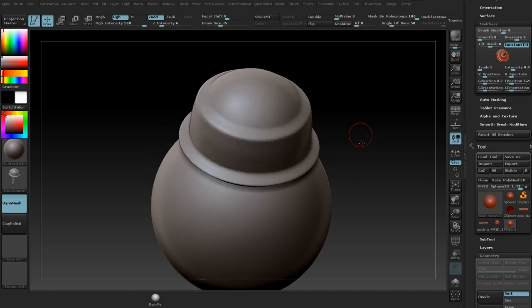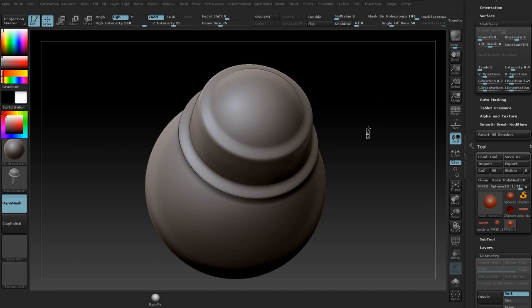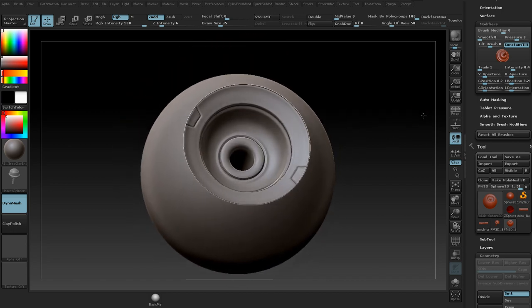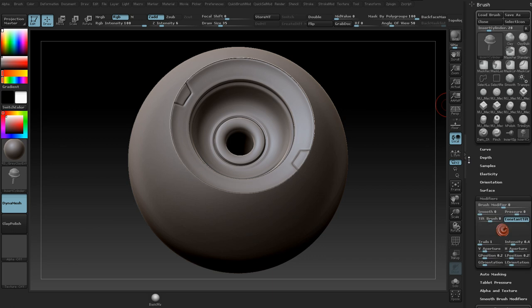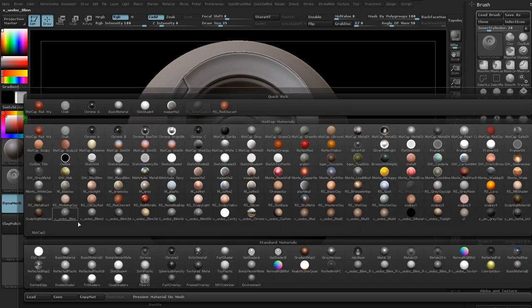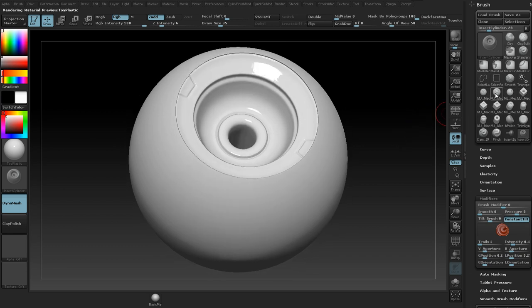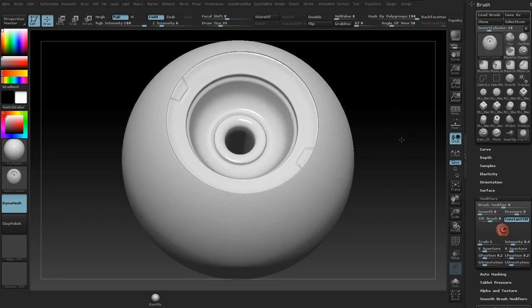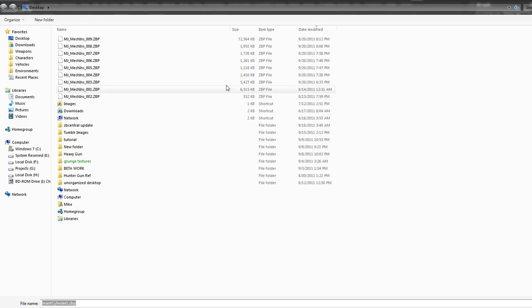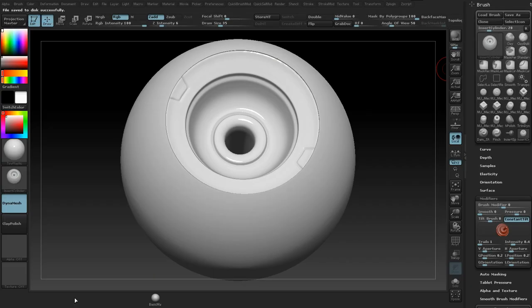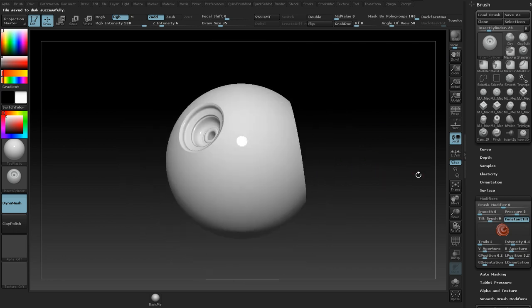And once you're done making the brush, it's good to make an icon for it so you can tell which brush is which. So I'm going to make it really big on the sphere, cut into it. It's going to look a little bit different. This isn't what the brush is going to look like, because the bigger you draw it, the more is going to be cut away. But if you go to the brush and then you hold Alt and click Select Icon, it'll make a print screen of your mesh that you have up right now. And so I went to the toy plastic material because that's the one that is used in all the other icons. So I want everything to match prettily. And then just Alt-click the brush icon, and then save out your brush. Or Select Icon and then save out your brush. And that's it.